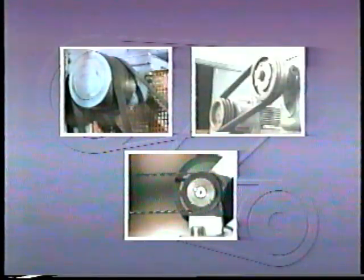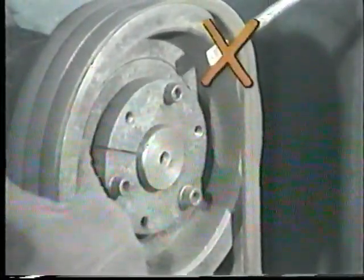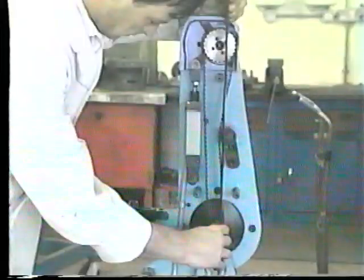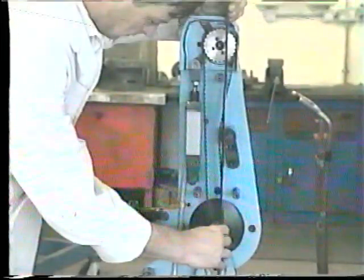Now, there are a few things about all types of belts that you need to remember. To prevent damaging a belt when removing it or replacing it, never pry it off its pulley or sprocket. Move one of the units so that the belt may be slipped off. If it has an idler pulley, move the idler pulley instead. Proper alignment of the pulleys or sprockets is essential if you're going to get the maximum efficiency from these drives. Take the time to line them up correctly.